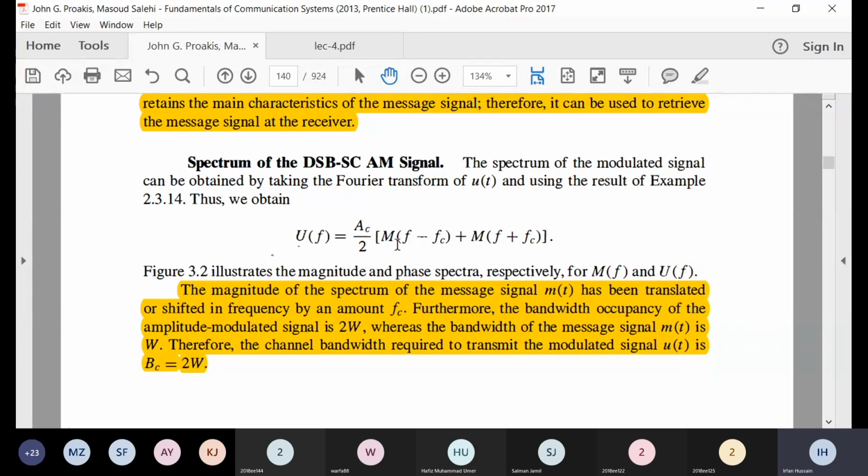So even if some students are not clear, they can see the example. Very simple, because once you multiply m(t) by e^{jωt}, you can see in the Fourier domain it takes M(f), its Fourier spectrum, to fc. But here, because each cosine contains two exponentials, one positive frequency and one negative, the negative will actually shift this to minus fc. All right, you can see that in the example.